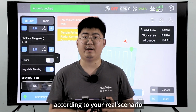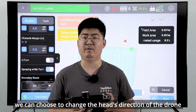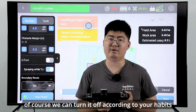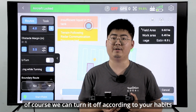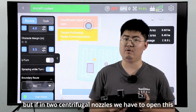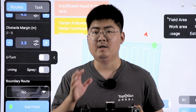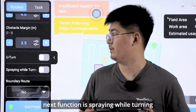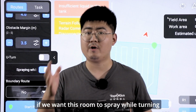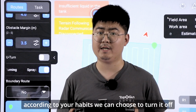According to your real scenario, we can choose to change the head direction of the drone. So, it's a function of U-turn. Of course, we can turn it off according to your habits. But if in two centrifugal nozzles, we have to open this. Next function is spraying while turning. And now, we can turn this on if we want this drone to spray while turning. Of course, according to your habits, we can choose to turn it off.